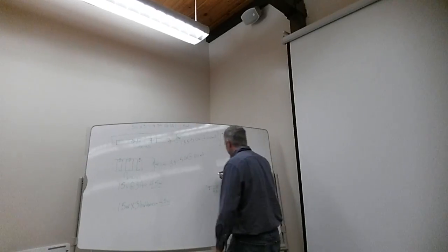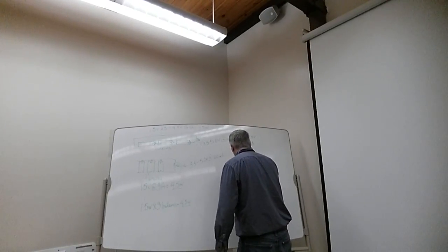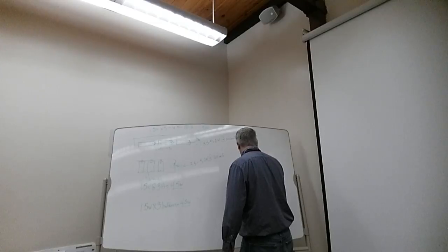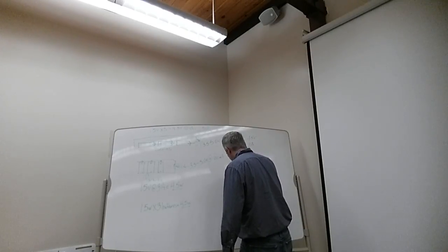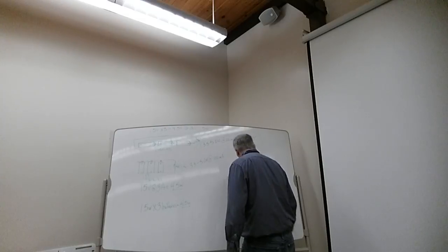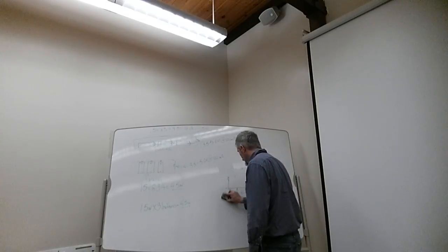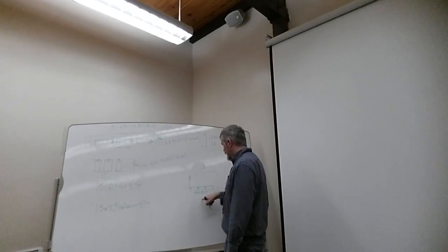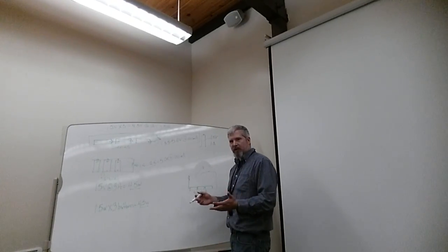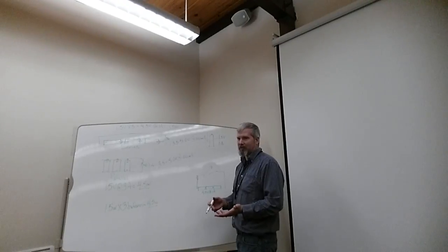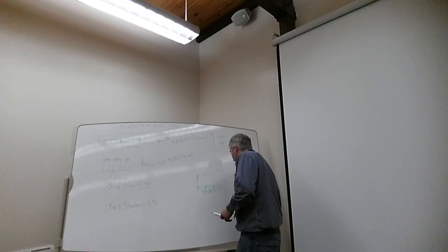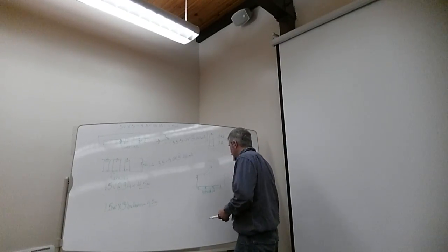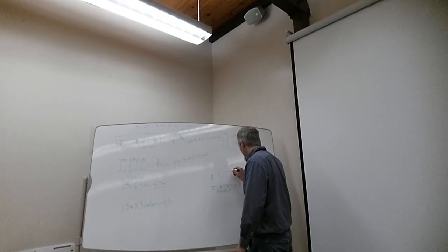So I stick in an LED here, and I stick the little resistor in there. Okay, and then let's say that this 4.5 volts runs that. We'd probably actually have to shrink this down to 2, so we'll put 2 LEDs in series with each other because we know we're good there.